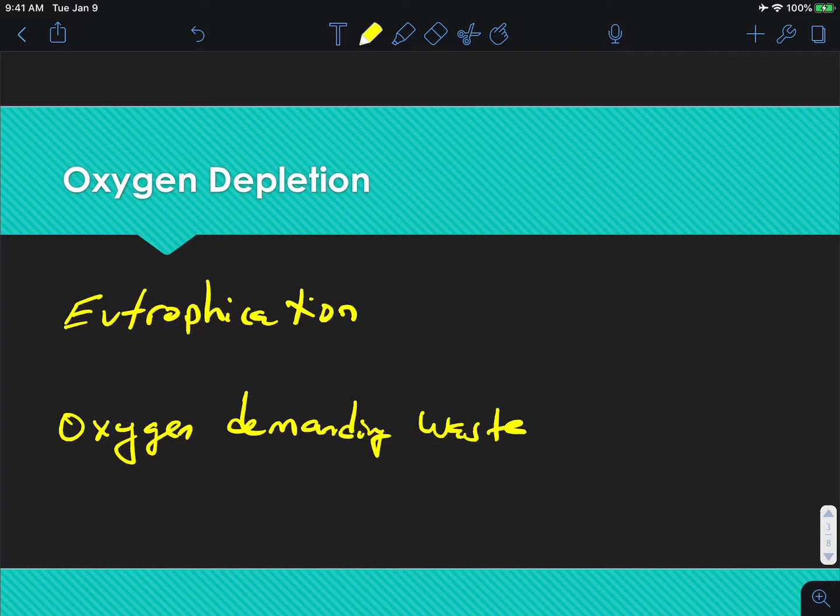So with eutrophication, as you should have gotten from your reading, you have this plant nutrient, this limiting nutrient that gets into the water. And typically the limiting nutrients, what we mean by that is nutrients that plants typically don't have enough of to grow. And specifically now we're talking about aquatic plants like algae, okay? Now plants in general are limited by basically two elements, nitrogen and phosphorus. But here we're talking about water systems, so we're interested in these algae. And their growth is limited. Now, these types of plants are just like bacteria. They're small, and they multiply really fast.